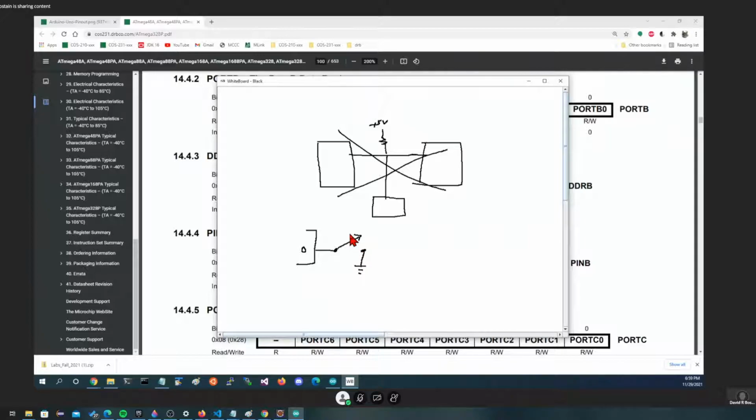It could be anything. So what I do is I externally put another pull-up resistor on this, similar but different conditions. This time I'm using an input. That time I'm using an output. They do serve the same purpose of having put the tri-state thinking on this box, but we'll keep it separate. So when I'm not pushing the button, I see a 1 because this is pulling it up to a 1. When I do push the button, because I have a resistor, current can flow, but I'm right at the ground, so I'll see a 0.